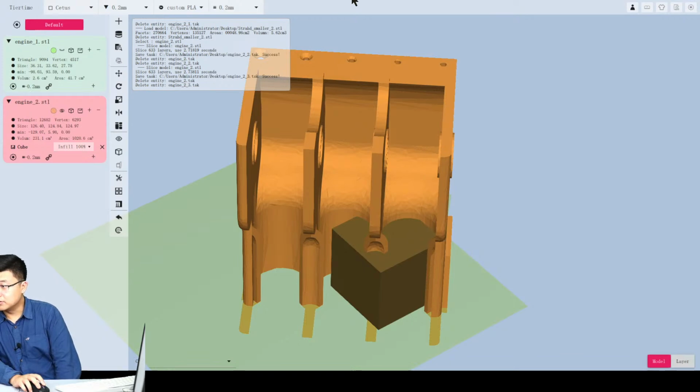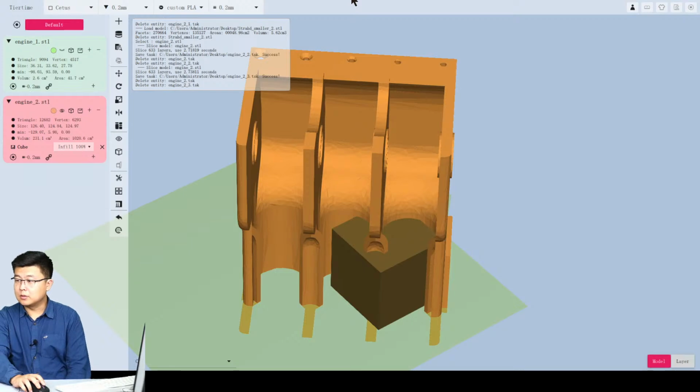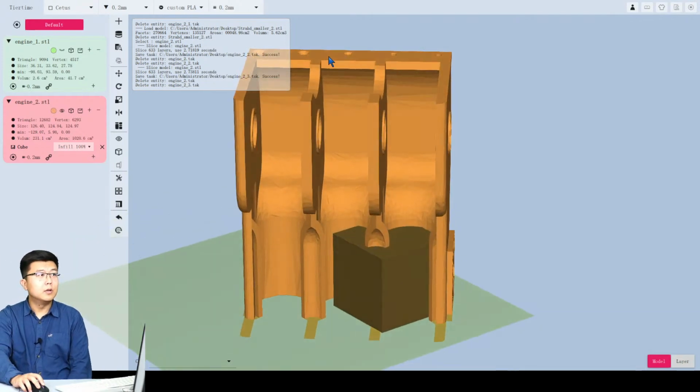Transfer custom material. One user asked how to transfer custom material from UP Studio 2 to UP Studio 3. Currently, there is no way to do the conversion. But actually, the setting structures are very similar in UP Studio 2 and UP Studio 3. So maybe you can take a screenshot and then set up all the values again based on the screenshot.